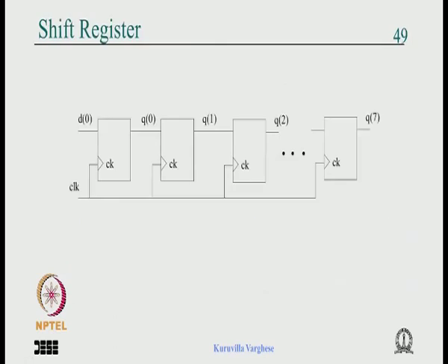And we looked at a shift register, how to model a shift register. Here it is an 8-bit shift register, which we have made a little awkward. D0 goes to Q0, Q0 to Q1 and so on, and you could write a loop within that clock event, clock equal to 1. That is one way.